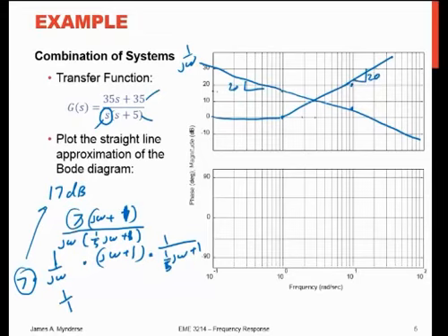And then I have one at 2, 3, 4, 5 with that same slope. Just eyeballing it there. In the phase plot, the phase of a pole at the origin is minus 90, right? If I draw my complex S-plane, or j complex plane here, well, this is the real part. This is the imaginary part. There is no real part to this. So whatever omega is, I'm just marching up the imaginary axis, and that angle is always 90 degrees.